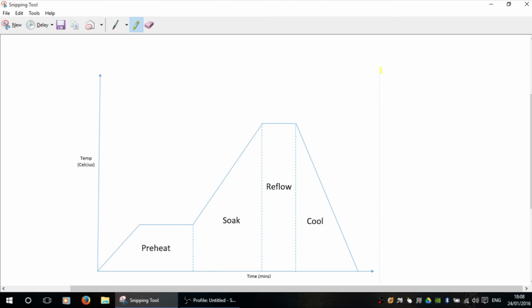So, for example, the South Bridge on a PlayStation 4 is a plastic chip, and it doesn't respond very well to a lot of prolonged heat and tends to warp. So we have to find either a different profile for it, or do as I do and find it easier just to preheat with a bottom heater on a rework machine and actually use hot air from a wand, because I tend to find that works quicker and creates less stress on the chip and actually encourages it not to warp.